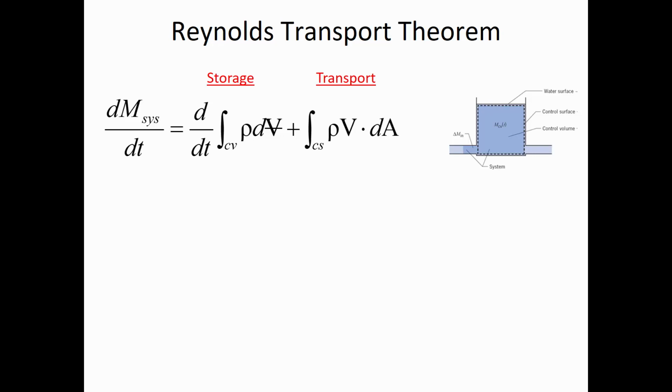Think for instance of a compressible gas. We could have a compressible gas entering a compression cylinder, and the volume of gas that comes in doesn't necessarily have to equal the volume of gas that goes out if the gas is entering and dispensed at different pressures. So volume is usually conserved if we're talking about liquids, but mass is always conserved.